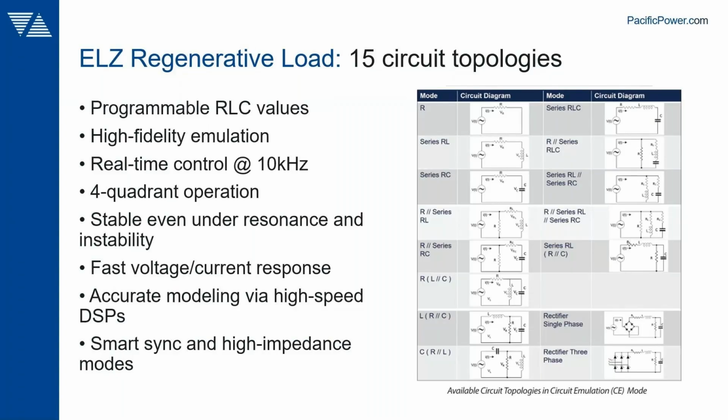So you have a very wide range of operation, keeping everything stable and preventing any resonance conditions. Voltage and current feedback, high-speed readback is available as part of these systems, and synchronization is done in real time as well, with the ability to have a wide range of impedance from high to low. So a lot of power, a lot of capabilities built into these electronic load solutions.